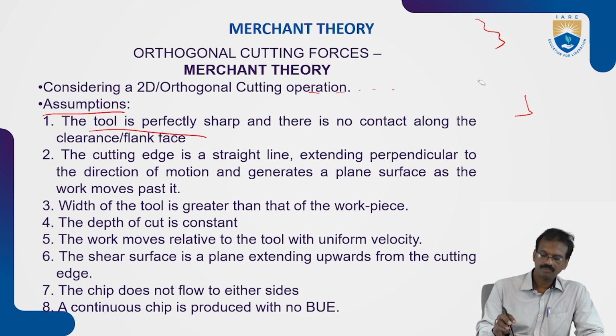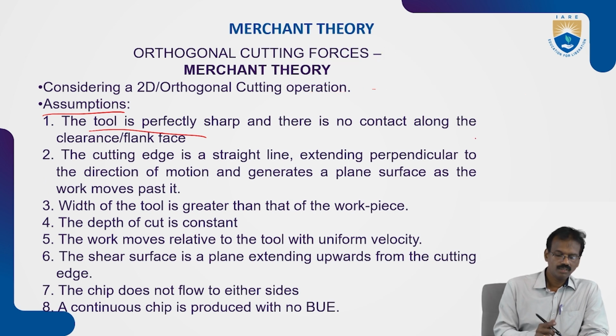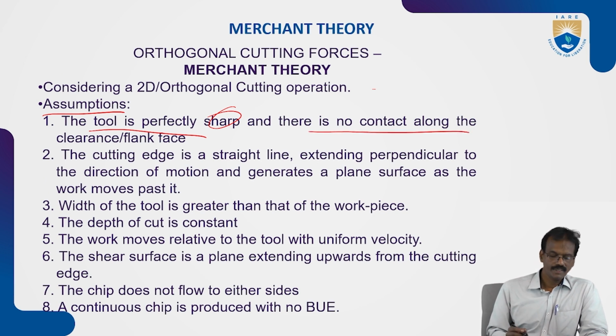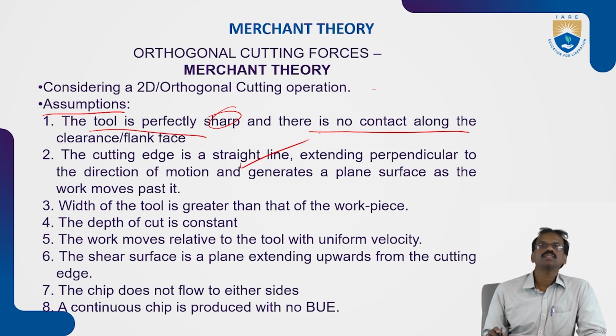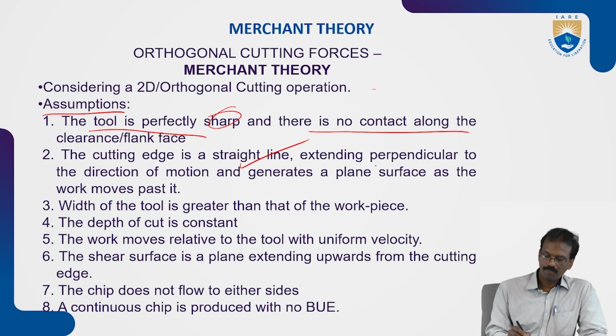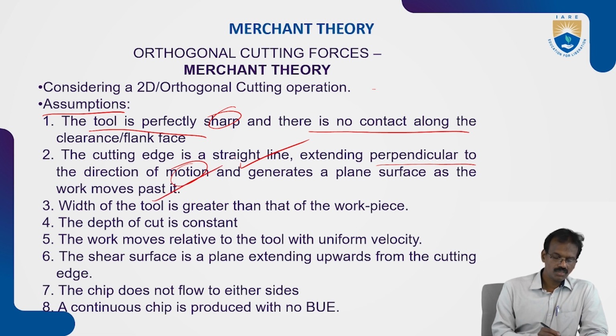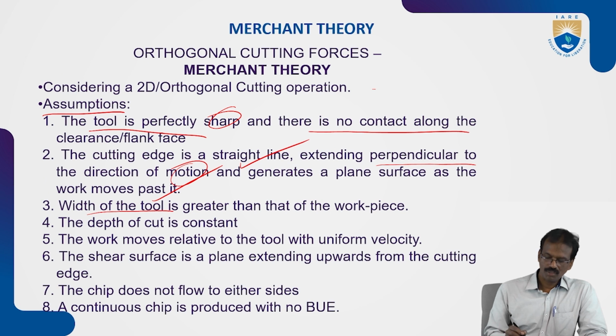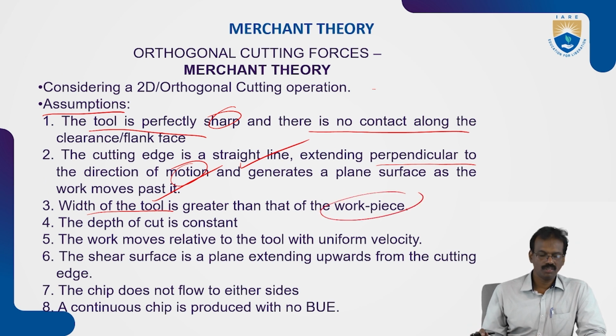The tool is perfectly sharp and there is no contact along the clearance and flank face. Next, the cutting edge is a straight line. You can see this one, extending perpendicular to the direction of motion, generating a plane surface as the work moves past it. Next, the width of the tool is greater than that of the workpiece. So that one is the assumption.